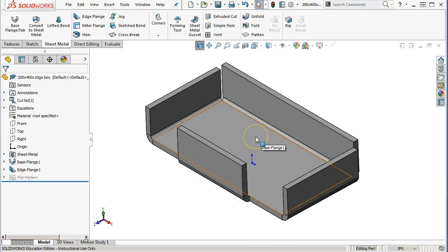And certainly this is just our quick intro, kind of getting through the process, creating the base flange, creating the edge flange as this bottom geometry. Does it matter which edge we pick, like the bottom edge? Yeah, no, it really shouldn't. It's going to bend from here to here and from here to here. I think of it in terms of the bottom edge, that's my preference to select, so I kind of do it consistently, I guess, but you should be able to pick either one to put the flanges in.